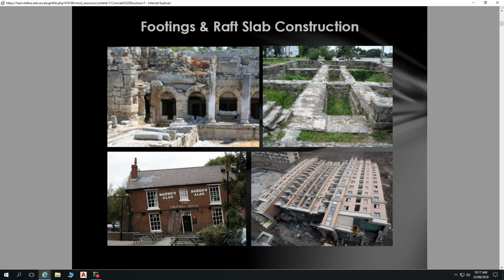We don't want moisture in buildings in general in terms of condensation and mold growth. Use a product called Sealicrete. It stops salt ingress into your slab. Is that an admix? Something that's added in? No, it's actually painted on afterwards. It's like a liquid that goes into the concrete by 20 mil.